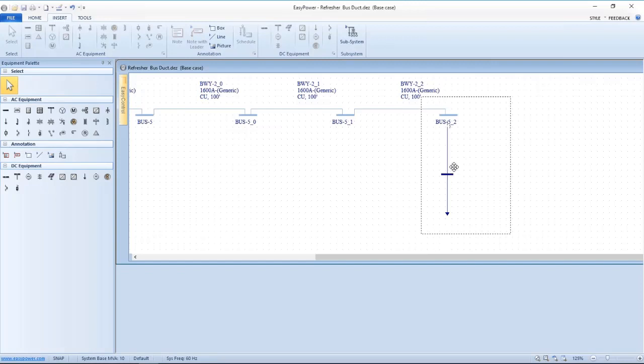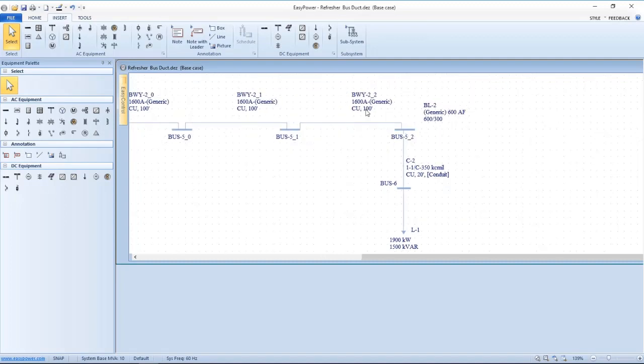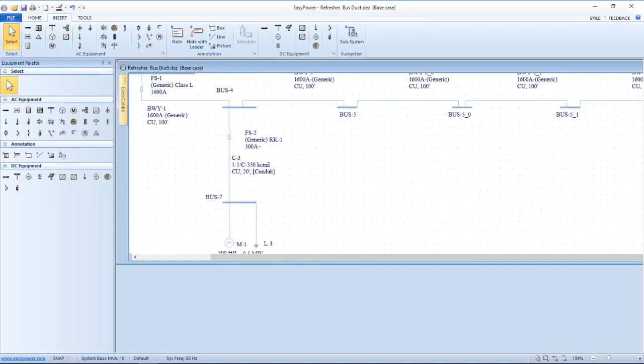And so we're just going to drop it on this last bus. All right, so this is a fairly hefty load, and it represents the lumped sum of all the loads within the last 50 feet. Whereas this particular lump total will be the total 100 feet here and 50 feet downstream. So consequently, at each bus, we're lumping the loads within 50 feet of that bus, with the exception of the very first link here. So now that I've done that,